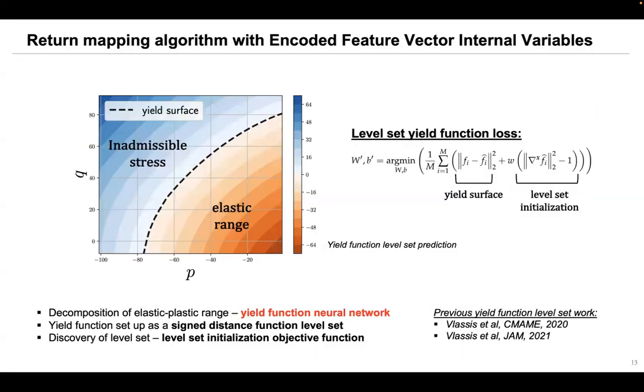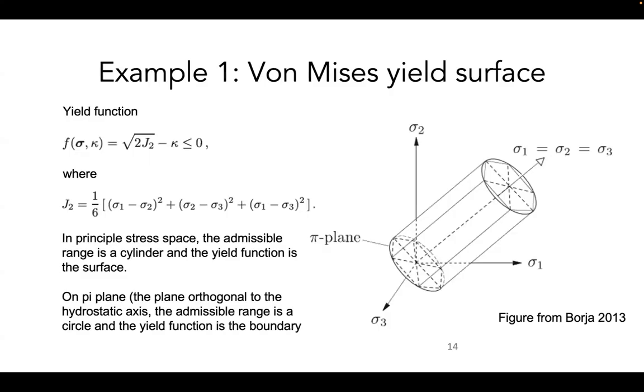So this is the yield function, and the yield function is not the yield surface. The yield function is one way to represent the surface in an implicit manner. The majority of yield surfaces are represented by implicit functions. As I mentioned before, you can write J2 plasticity.